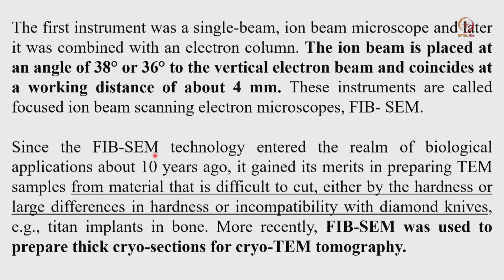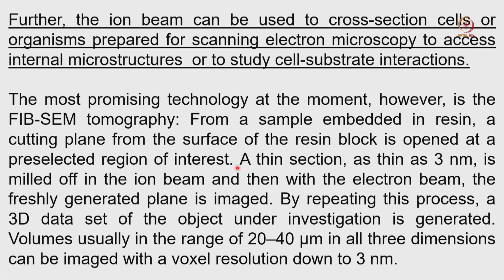Since FIB-SEM technology entered biological application about 10 years ago, it has gained its merit in preparing TEM and cryo-EM samples. For material that is difficult to cut, we cannot use a cryo ultramicrotome, either because of hardness or a large difference in hardness or incompatibility with the diamond knife. So, those are the cases where FIB-SEM is really helpful, and also after this sectioning it is not going to leave any knife mark on your sample. That is another good thing when we want to use FIB-SEM.